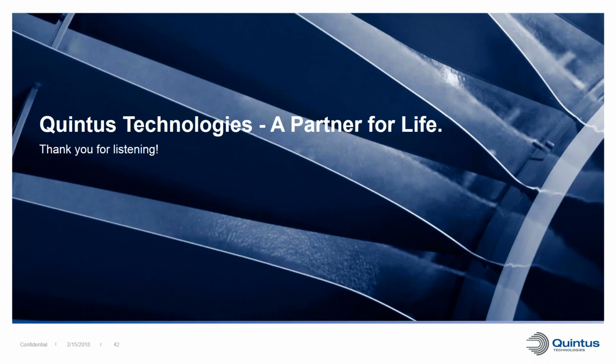Okay. The next question is from Susanna. In the case of 3D printed metallic parts, do you think that HIPing is able to eliminate internal porosity in which argon gas is trapped, and also in the case of nitrogen gas? Okay, so that was a little bit what I was talking about. In the case of argon, you will not be able to diffuse the argon into the metal. You will decrease the pore size a lot, normally below detectable limits, but you will have a smaller high-pressure argon pore there. In the case of nitrogen, it will diffuse into the metal, at least for most common metals. So then you can close the porosity completely.